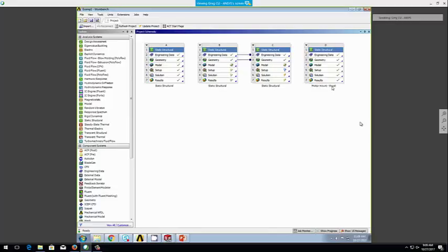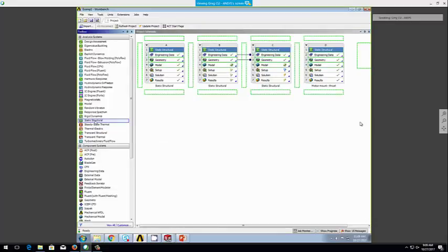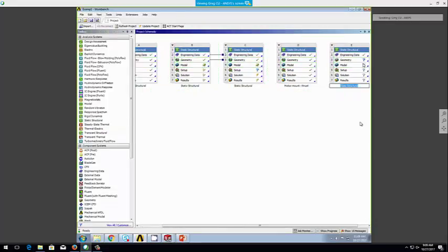What's a VN diagram? Well, it's really the envelope that you can fly your airplane in without stalling and without breaking it, and relates the airspeeds to the maximum expected structural loads. For regular aircraft, there are sets of FAA guidelines or requirements for the VN diagram of the flight envelope.